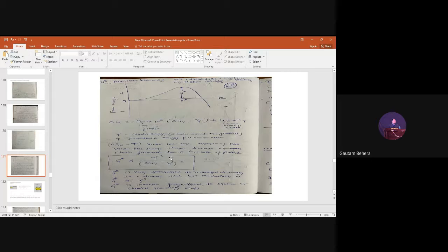Now this is an important term. You have to remember from this part, I am getting a conclusion, this is our final conclusion. G star is proportional to gamma to the power cube, the interfacial energy term, and the square term is the chemical free energy or volume free energy. Which one is more dominating then?